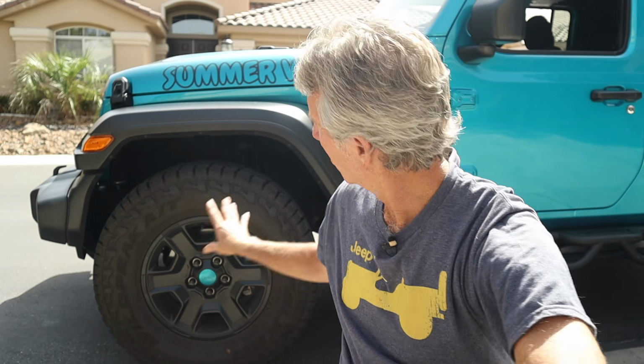So one of the most important things that JSCAN lets you do is change your tire's diameter size in the engine's computer. One of the first things that many Wrangler owners do is go with larger diameter tires because it's better for off-road and bigger is better. But when you do that, it messes up your speedometer and also your computer's estimated gas mileage. And so to get those correct, you actually have to go into the computer and change that tire diameter size. Now you can go to the dealer and have them do it, but they charge an awful lot to do that, and you can do it relatively inexpensively with JSCAN.